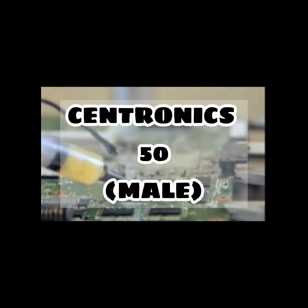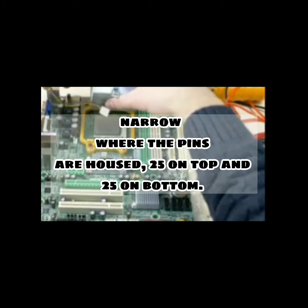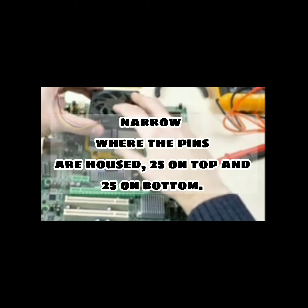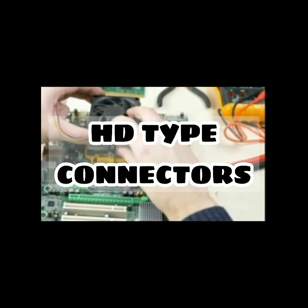Lastly is the Centronics 50 or male. Instead of 50 pins sticking out of the connector as found on a SCSI DB50 male connector, the end of Centronics 50 male connector is constructed of one long, narrow row, where the pins are housed 25 on top and 25 on bottom. The HD type connectors has 3 types.